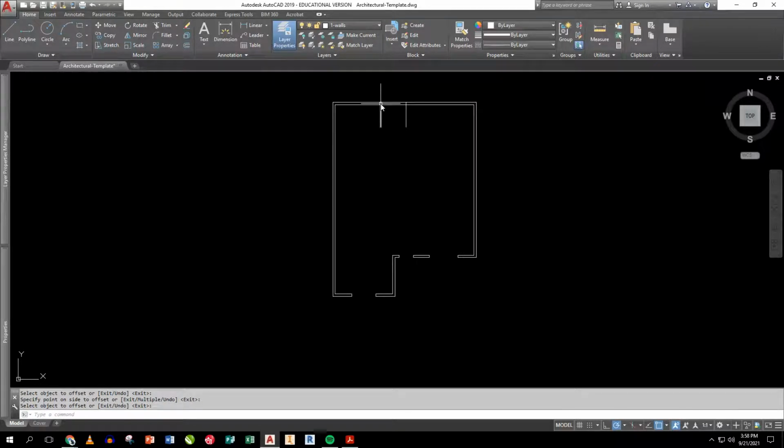Now, how I got that is from here to the corner of the wall on my plans is actually 2'10", and the next one to the center, 2'6", and the next one is 2'10". Well, 2 foot and 2 foot is 4 foot, and then I've got 16 inches besides that, which gets me 5'4", because 16 inches is 1'4". So it's 2 feet and 2 feet and 1 foot 4 inches all together. So that's 5 feet 4 inches. Now I'm in the middle of those 2 windows.